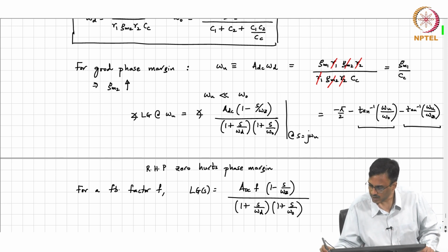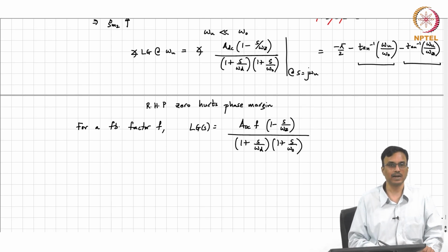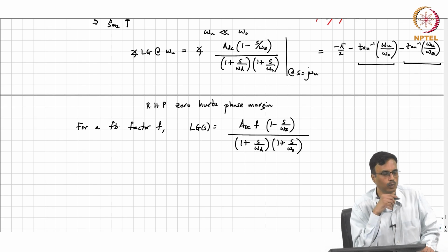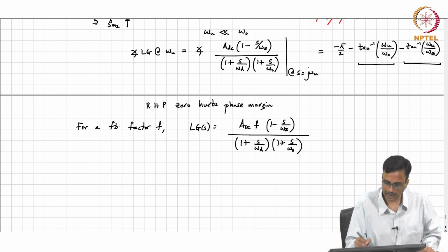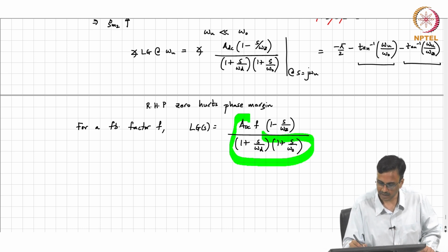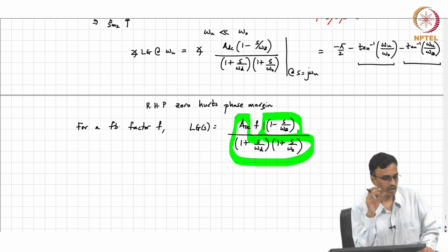Okay. So, what is the worst case feedback factor for stability analysis? For what values of f would we have to be careful about stability? So, let us say all of this is exactly the same, none of that is changing. Because the op amp is the same, we are varying the feedback factor around the op amp, correct.